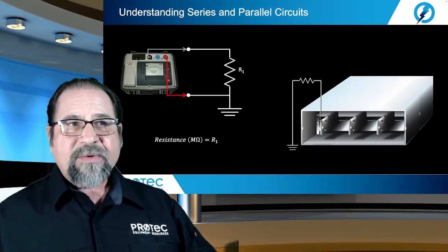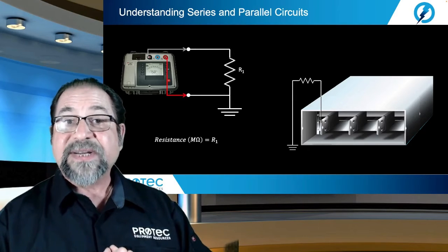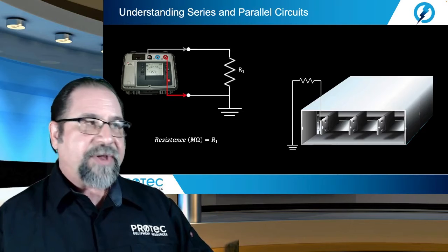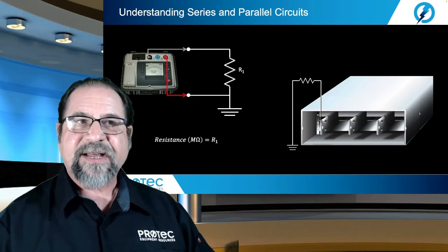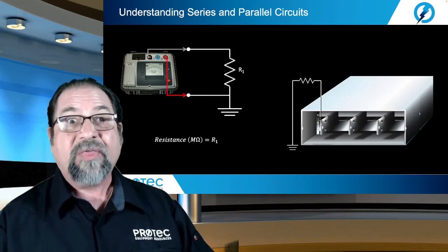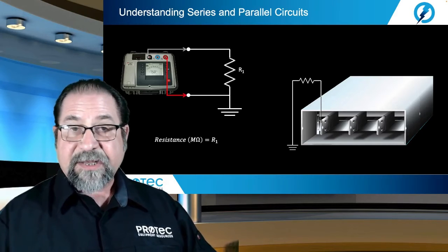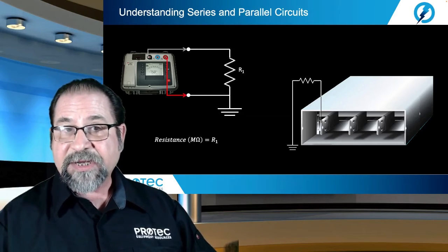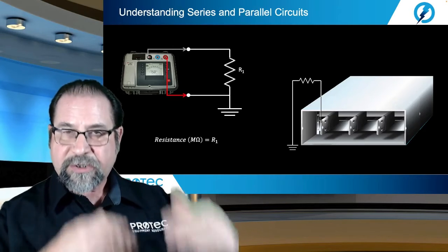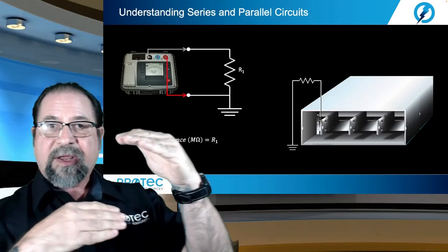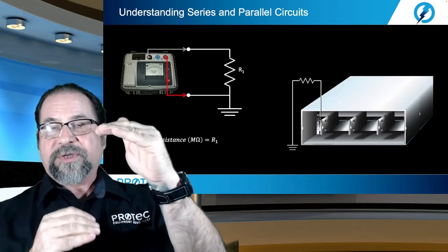All right, now next let's take a look at doing the insulation resistance measurements. Now here we would use a device like the megohmmeter, insulation resistance test set, or sometimes simply just referred to as the megger. Now here, basically the way this test set is going to operate is we are going to apply a known voltage across 2 conductive surfaces that are isolated by an insulation. Okay. So we put a known voltage across.